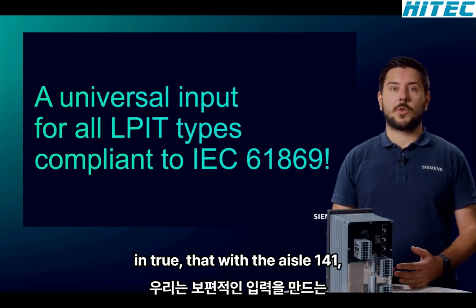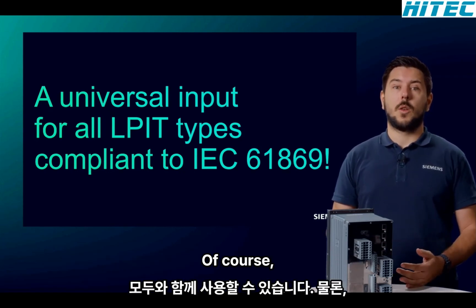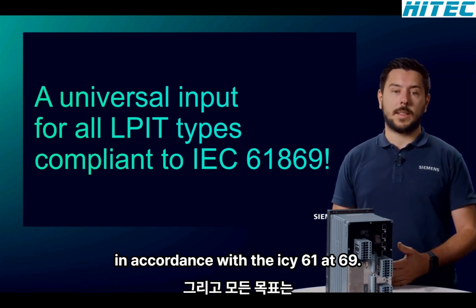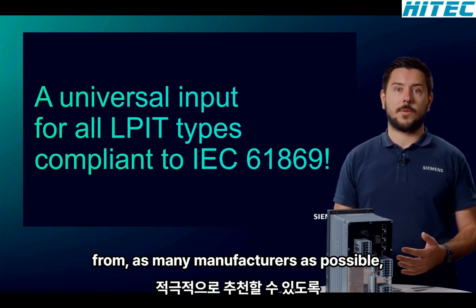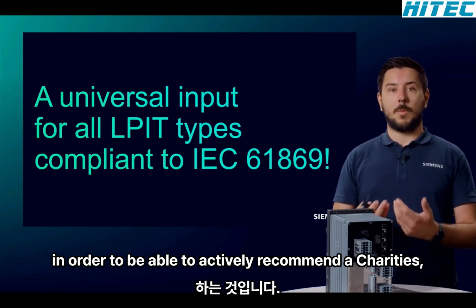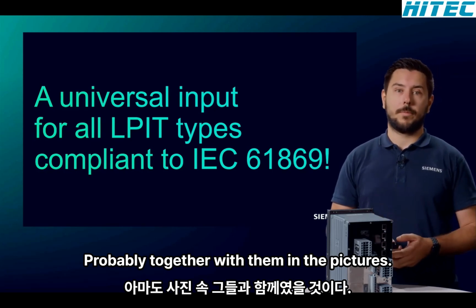All these aspects now ensure that with the IO141, we have succeeded in creating a universal input for use with all sensor types from different manufacturers. Of course, it is essential that the sensors have been manufactured in accordance with the IEC 61869. And our goal is to be able to offer all users compatibility with as many sensors from as many manufacturers as possible. In order to be able to actively recommend LPITs, it is of course necessary to carry out detailed tests, preferably together with the manufacturers.